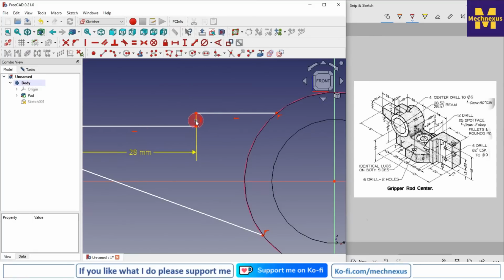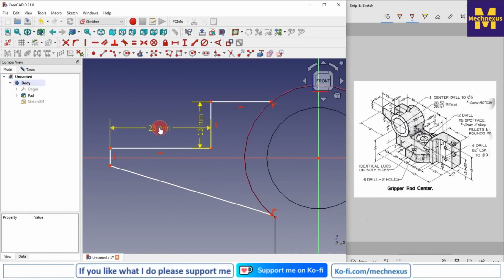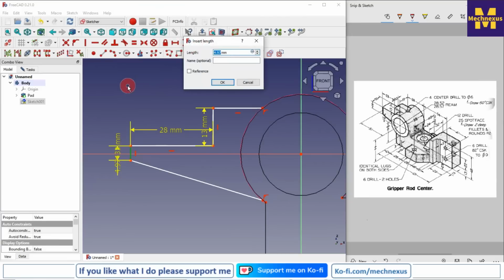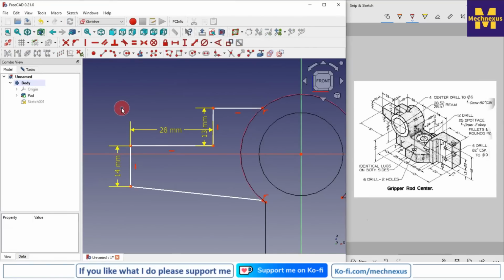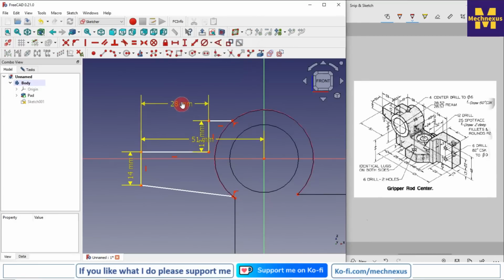I will move it down, and this is the 13. And I can move it down. This is the 14, this line. So I will select it and give the vertical dimension of 14. And we can see here 51 dimension, outer edge to the center. So I will select this point and the projected arc point and give it 51, and I move my dimensions.